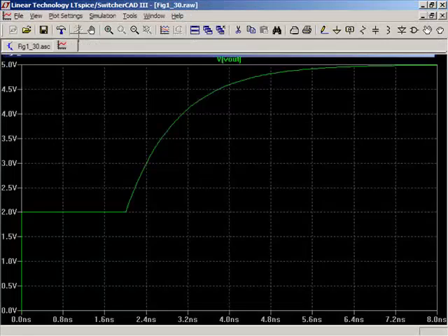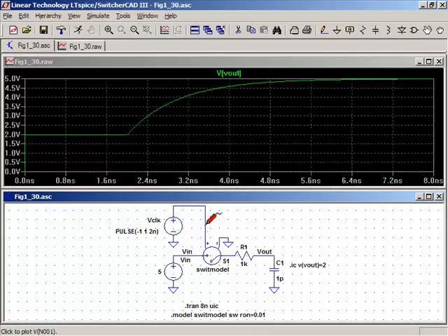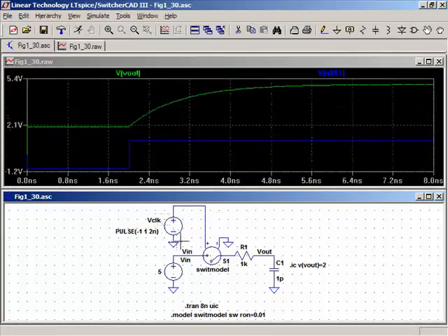Let's run the sim. First thing I'm going to plot, I'll just right click on this node. You see that it goes through ground. Let's see if I can put ground on there. Nope. This pulse is set up to go through ground at this time, which closes the switch. When the switch is closed, the 5-volt source is connected to the 1K resistor and the 1 picofarad capacitor, so it behaves just like a pulse source.